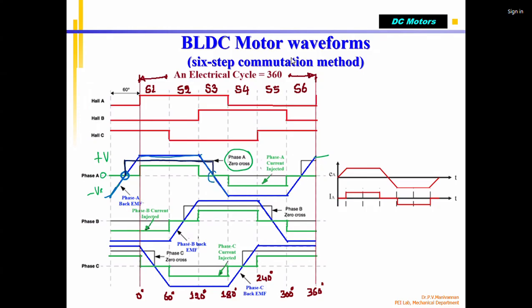So it is coming from positive to negative. Again, it crosses at the zero crossing point, and you can see the output of the phase detector becomes 0. This is the phase detector output. It is supplied to the motor controller, which in turn generates the green waveform, the voltage waveform applied to the coil. This is generated based on the zero crossing detector.